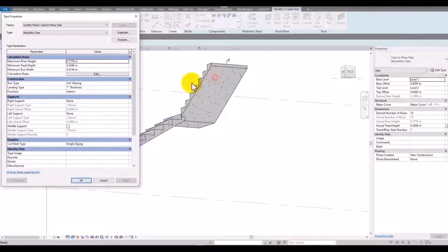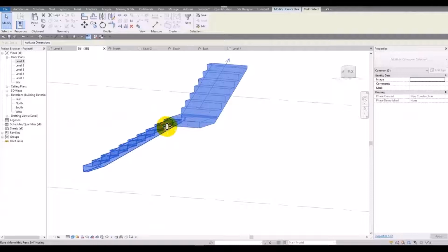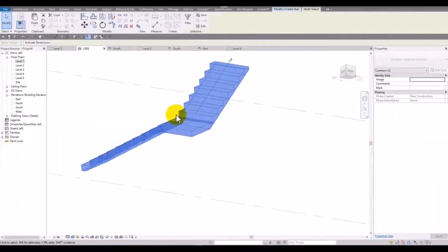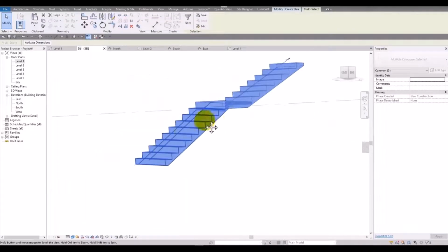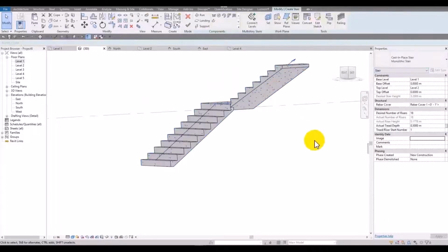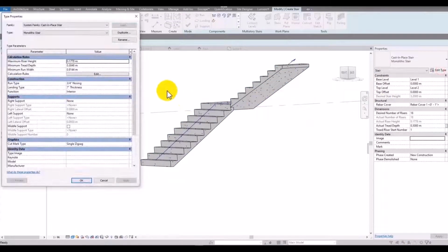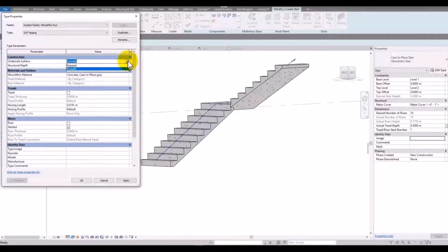The connections which you have here for your stairs and the mode which you have for landing is different. How we can control them here in edit type, and I change this to step. Okay, apply and see what happened.